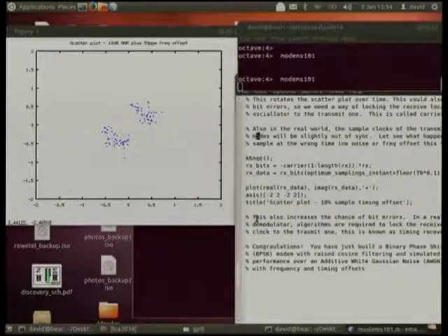Now also for a real-world system, the transmitter will have a D to A converter with a sample clock. It might be clocking out samples at a million samples a second. The receiver will have an analog to digital converter that's sampling the signal at, say, 1 million samples a second. But those clocks are at two different sites. They're running at different frequencies, just slightly off, with different temperatures and things. So one will be a little bit out compared to the other. That means the transmitter and receiver are at slightly different sample clocks, which once again leads to distortion in the modem and possibly bit errors.